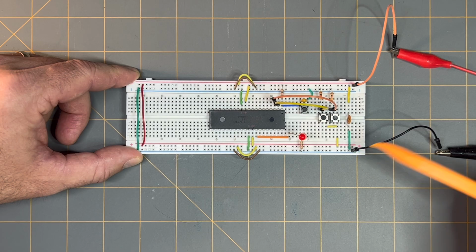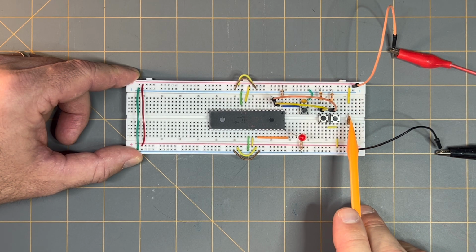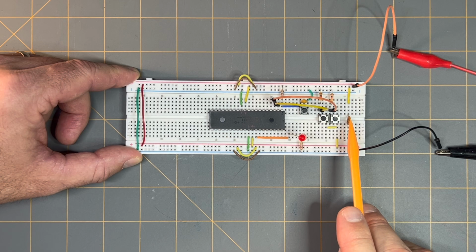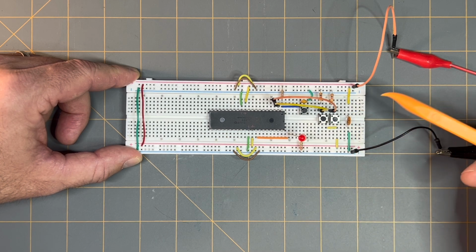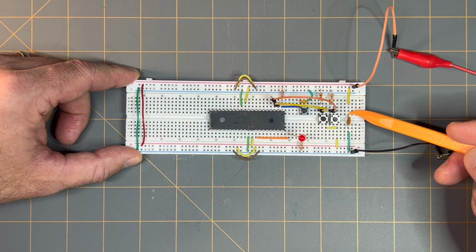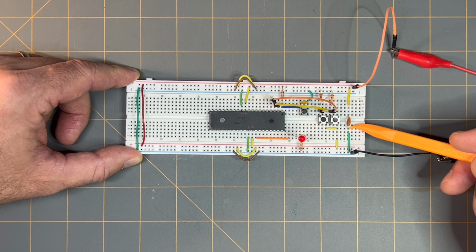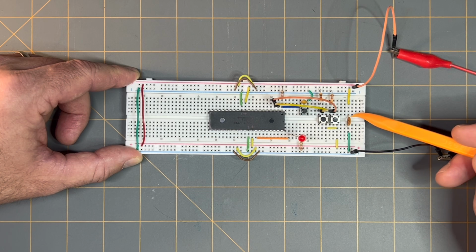So from there we have our two initial connections from our power supply going into the breadboard, the positive and the negative. And then what I did next was I placed a 0.1 microfarad ceramic capacitor, and I placed its legs into the points E4, and G4. So that crosses this center gap of the breadboard.